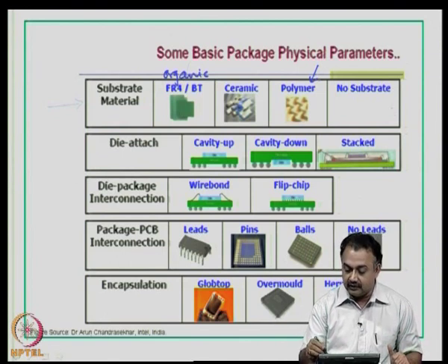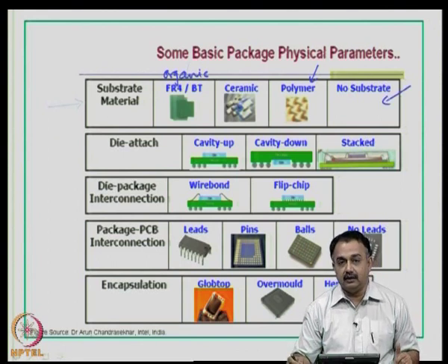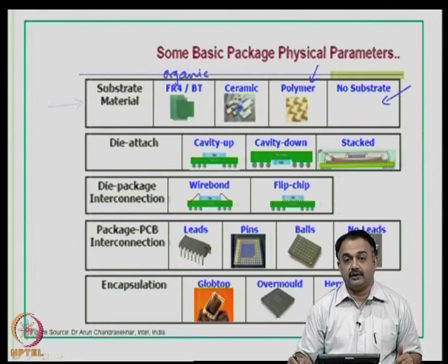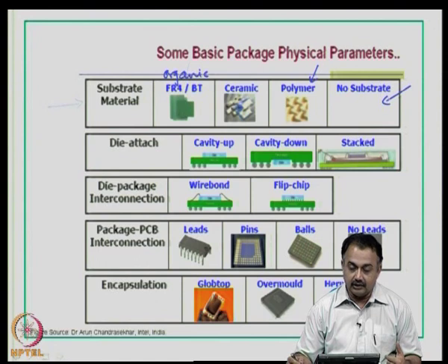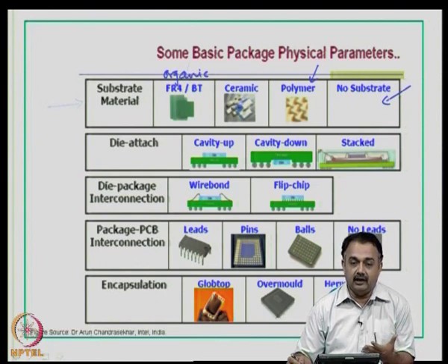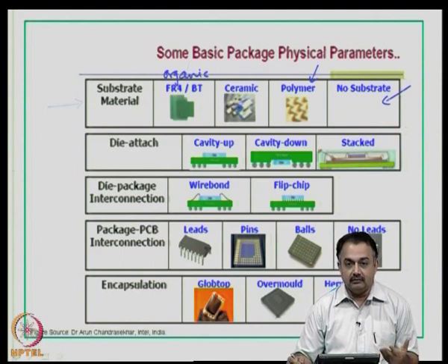You could have no substrate. So, is this possible? Can you have a package with no substrate? When you say no substrate, there is no platform for the die to sit on. But if you look at the literature, some packages have been made with no substrate, in the sense that there is a die which is immersed in an organic resin and then cured, and then the interconnects in terms of leads come out from the organic resin.